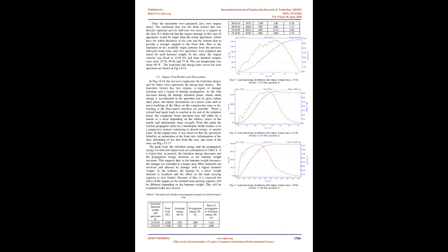3. Low velocity impact testing. Composite sandwich structures have been recognized as having higher bending strength, lower weight, and higher durability. For composite sandwich structures, they usually contain laminated composite skins. It is well known that laminated composites are vulnerable to impact damages, in particular to low-velocity impact-induced damages. After a low-velocity impact, the residual strength or stiffness of the laminate can be reduced significantly.